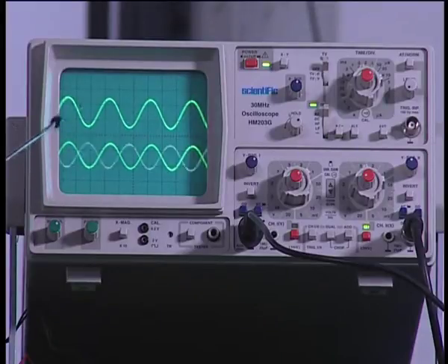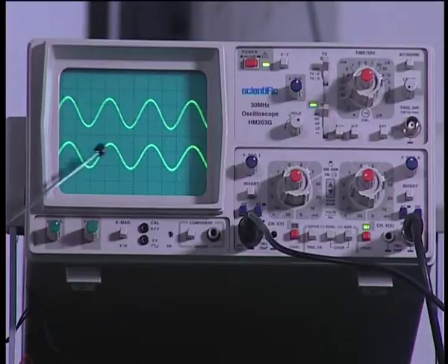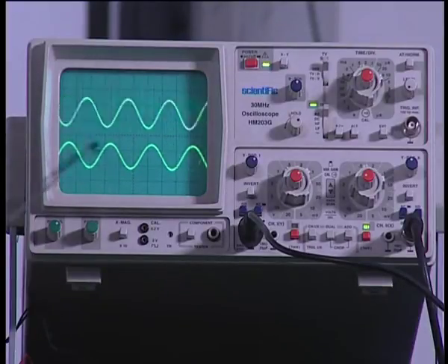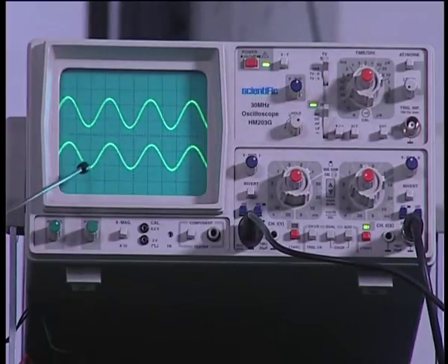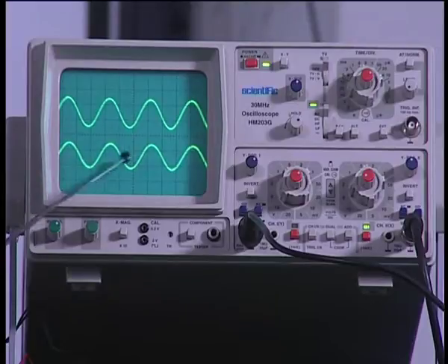But when I change the potentiometer, you would find one of the traces, the output trace, will show a shift that corresponds to the phase shifting that I am talking about. For the same RC network, if you change the value of R and C, you will get different phases. Therefore, you would find the shift in the phase as seen by the shift in the trace that you see on the oscilloscope.